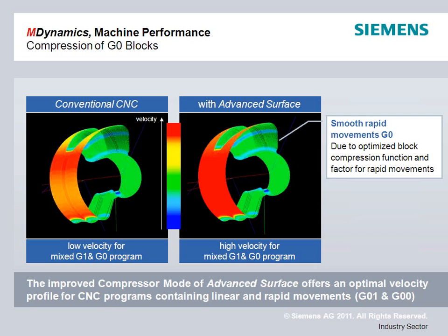While if you're thinking about a job shop type program, that doesn't sound like a big advantage, and if you're thinking about a 2.5D mold and die part, when you're doing a G0 block, you're retracting, getting out of the part to do a tool change or get over into another hole, you're not doing a lot of moving around. Where this really comes in is 5-axis programming, where you're going to have to pull out and reorient your head as you're moving to your next feature. This allows you to pull out, stay reasonably close to your part without having to do a very deep retract move, and reorient with a handful of short blocks as you're moving to the next feature. So this does have some substantial time savings when you get into large 5-axis machines that have long pivot lengths.